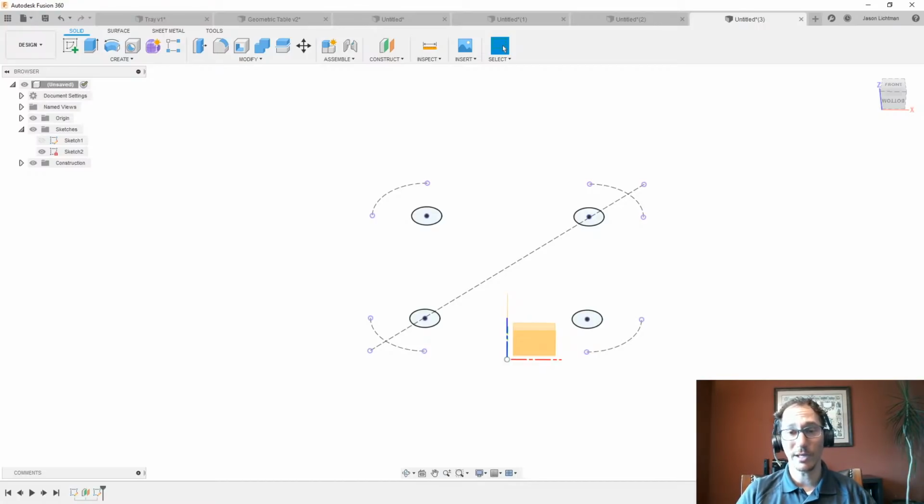And by the way, they don't have to be on different planes. So you could have all of this be on the same exact plane. You could just work in one sketch plane for everything and just have a sketch that represents the holes you're going to drill through this model, a separate sketch that's going to represent the ribs you want to put on this model, a separate sketch that's going to have all sorts of other things. One of the keys here is some people think that you should put absolutely everything in your model into one sketch. And I would say I don't exactly recommend that.